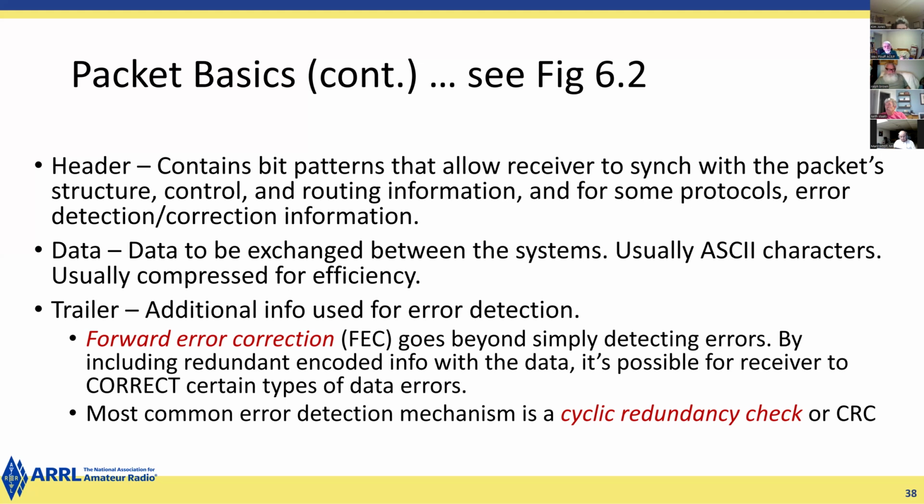Forward error correction is where you use extra bits so that when the data is combined and decoded in the receiver, you might use 50% extra bits, 50% more bits than you use to send the raw data. You might use twice as many. And what that does is it will allow you to correct errors. If it's 1 bit off, the decoder says, oh, this is really the letter E or the letter Q, but it doesn't get them confused.